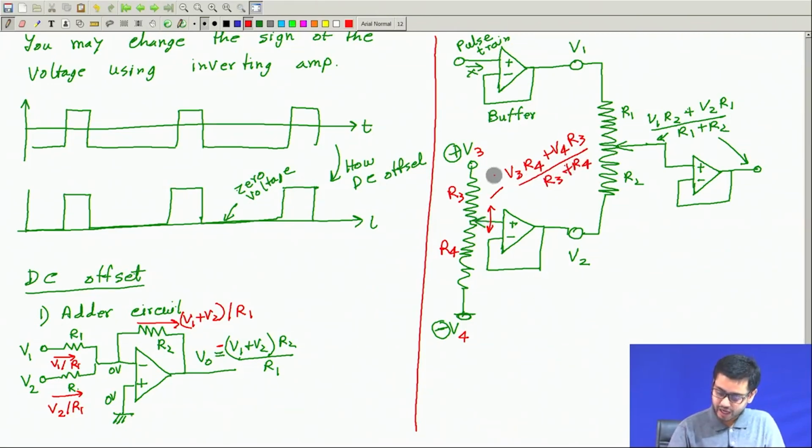Okay. So, you can bring it up or down. If you bring up, this voltage will be more positive, because then R3 is reducing and R4's effect will be more. Okay. V4 is negative, let me write this minus. Okay, fine. So, this way you can change this voltage. This is a DC voltage. So, this DC voltage comes here, and this DC voltage gets added to this V1, which is same as this pulse train, right.